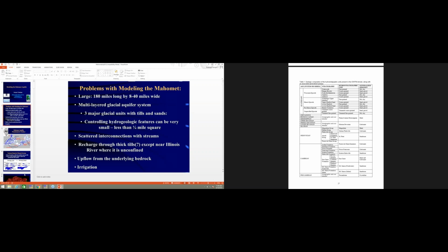And then sometimes it's not the geology, but sometimes like here, where the Mount Simon is fresh water versus saline, we put in a different hydraulic conductivity for that just to account for the density difference, the salinity. And so we have the Mount Simon divided up into 2 layers. We really don't have to do that. We could just have 1 layer, based on the geology. But here, let's go ahead and do it a little differently.